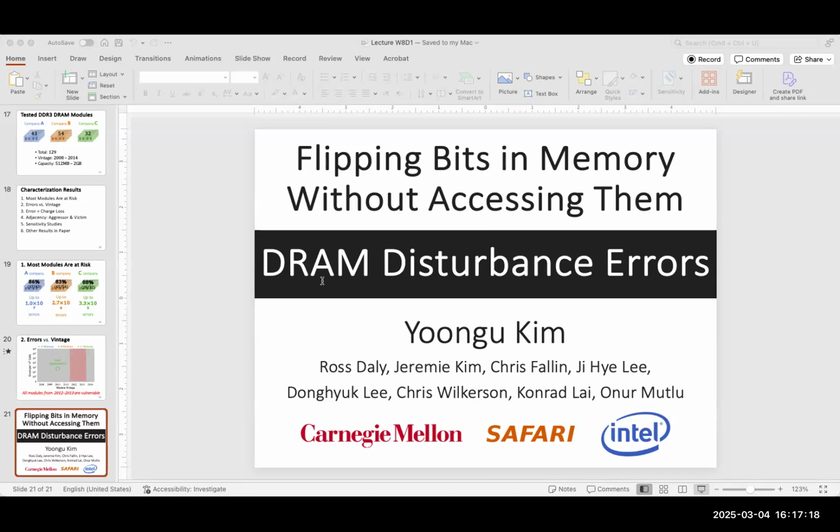Second, if you are storing the checksum for every row, you are reducing your effective capacity. I will not say exactly by 2, but let's say roughly by 2. So first, it will not work because we can induce errors on the checksum. Second, we are reducing the memory capacity effectively by half.